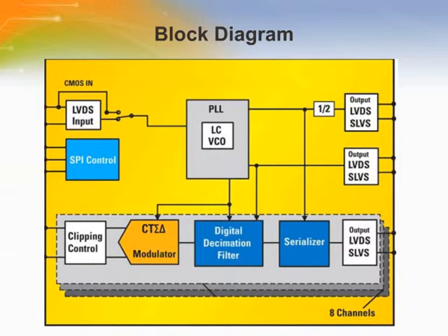The internal digital decimating filter provides an intrinsic anti-alias filter, eliminating external analog filter components and simplifying multiple channel designs. The PLL is critical to the operation of the ADC12EU050, and the PLL also provides the bit and word clock outputs. The SPI control interface gives uncomplicated user access to the ADC registers.